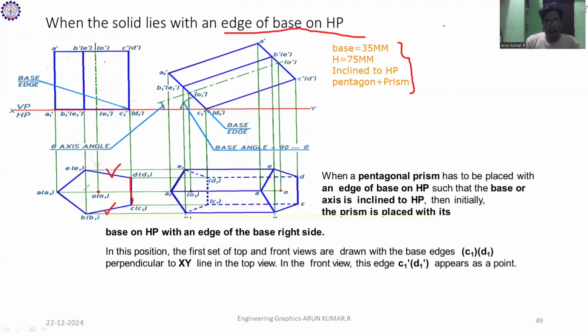After that, take the compass and measure the base length of 35 mm, and cut arcs from these two points. Where they cut, you get another point, which is the last side of this pentagon. Once you construct all the lines, you get the pentagon shape. After you complete the pentagon, you give the names correspondingly.